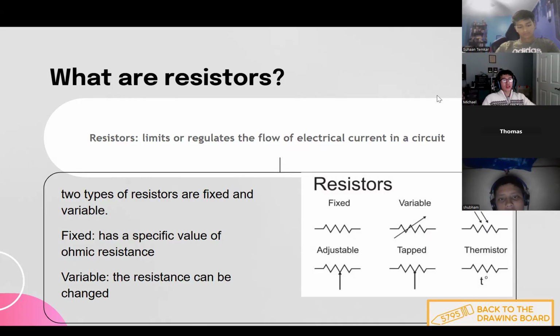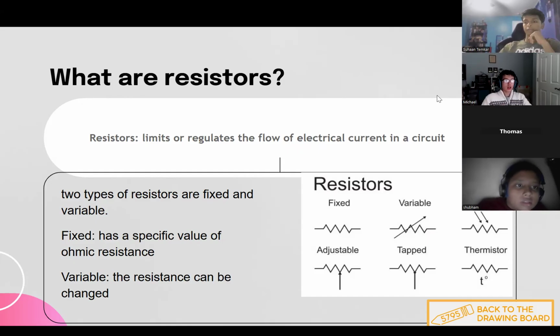And this is useful. If you've ever seen those street lights that turn on at night, or one of those little garden lamps that turn on by itself at night, that is a photoresistor. All it's doing is sensing when the light gets dark enough that it needs to turn on. The circuit senses that the resistance is lowered, so it turns on the light.